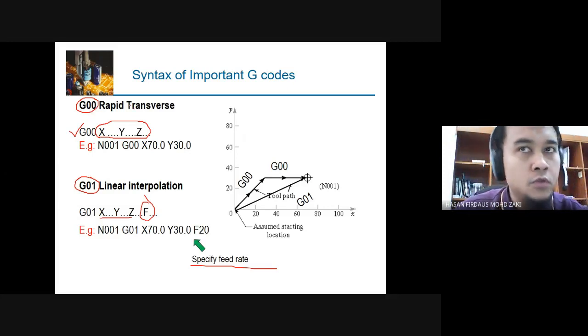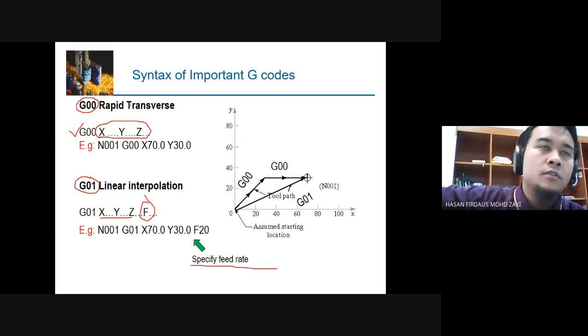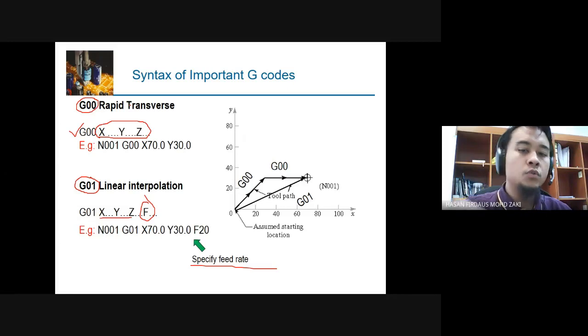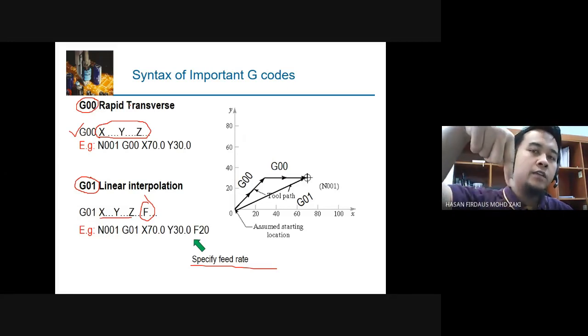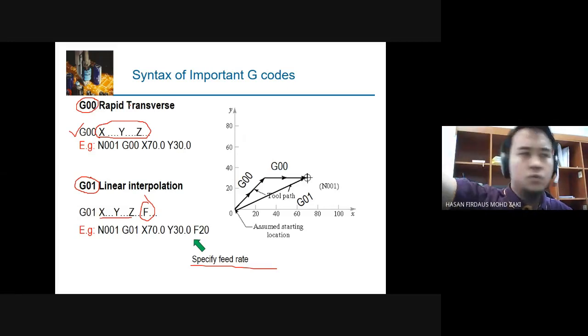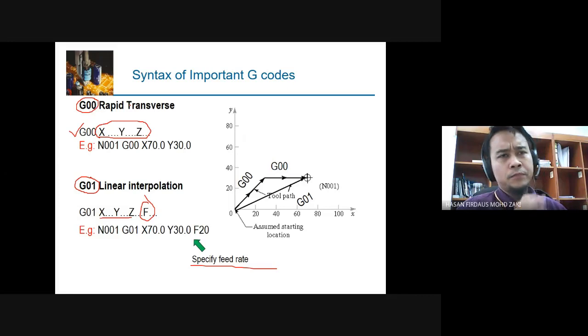Okay, so for example, you want to go very quickly to the datum, or for example you want to drill, right? So you drill, you retract and you want to go to the next position, instead of going slowly to the next point, you go very fast, right? Because you know that the path has the clearance, so you go very quickly, and then drill, retract, move quickly, drill again, right? So this one will of course save you lots of time.